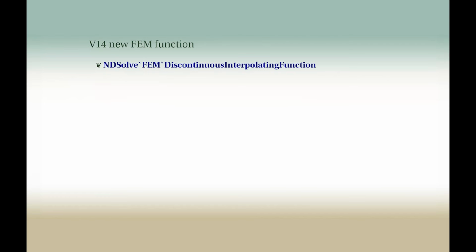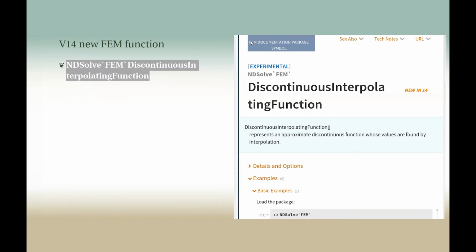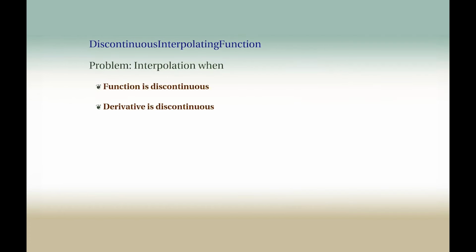So now we change gears a bit. There is one new addition from the finite element functions that I'd like to show. In the NDSolve finite element context, we have a new function called DiscontinuousInterpolatingFunction. There's a reference page for it, and some additional documentation. Interpolating functions have problems when the function itself is discontinuous, and also when derivatives are discontinuous. That's something this discontinuous interpolating function tries to tackle.